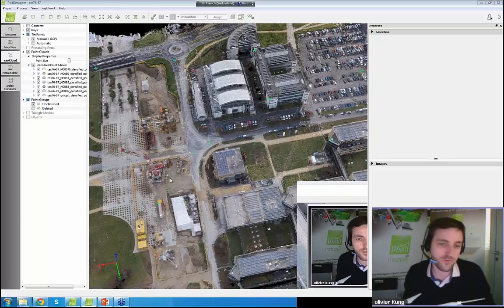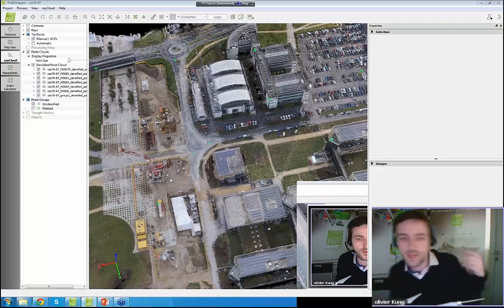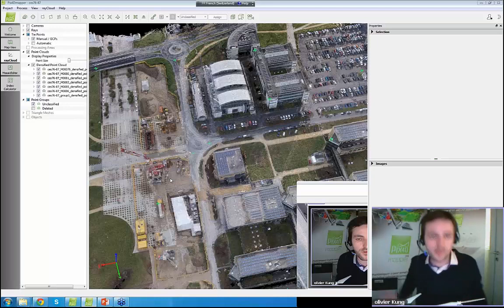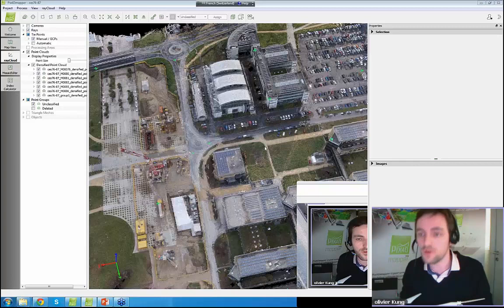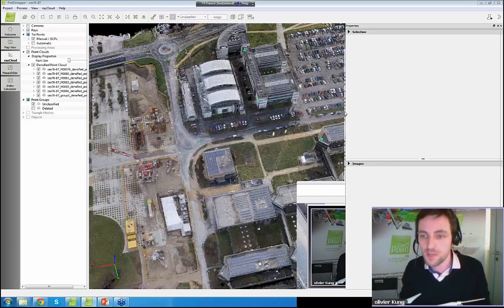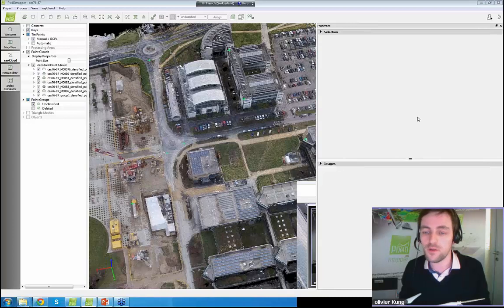And so you first do a gridded mission with the app, and then you do a free flight mission with the app again, and then you follow the instructions on support.pix4D.com on how to merge properly. Actually, there is a whole webinar about how to merge different flights that are quite dissimilar, and that was given a few months ago. But as a tip, to do this merge, it may happen that everything works automatically, but we would suggest using some manual tie points, just as I did, to improve the quality of the project.